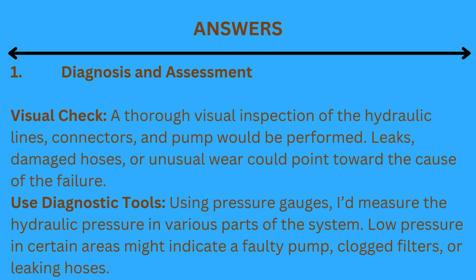Visual check. A thorough visual inspection of the hydraulic lines, connectors, and pump would be performed. Leaks, damaged hoses, or unusual wear could point toward the cause of the failure.